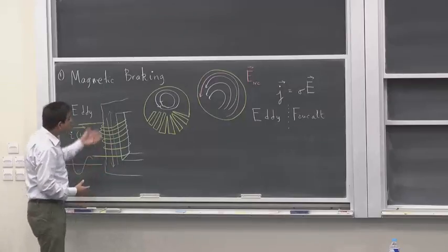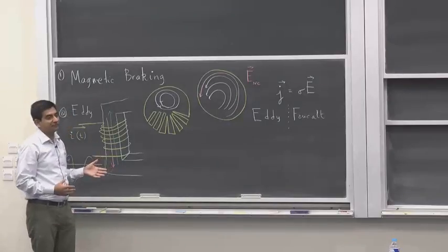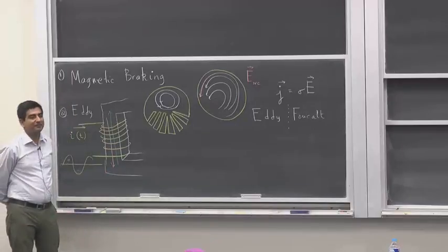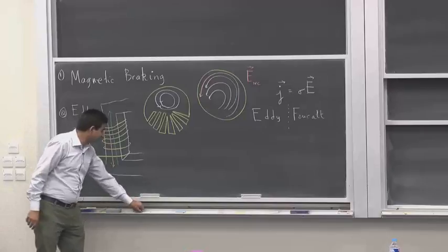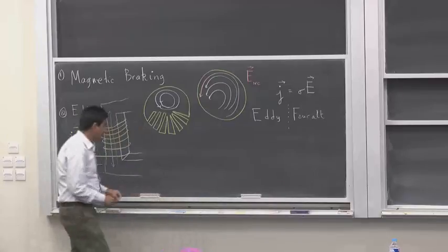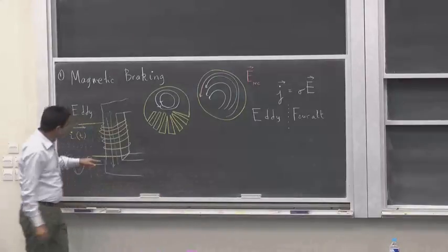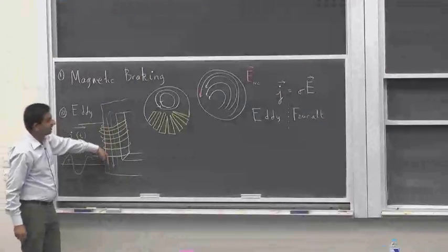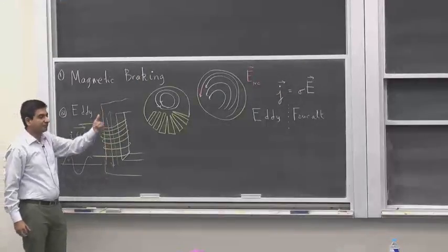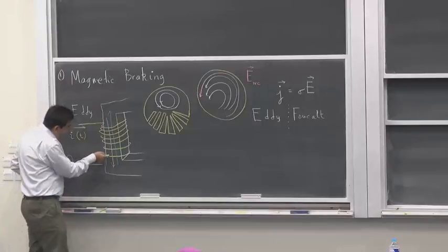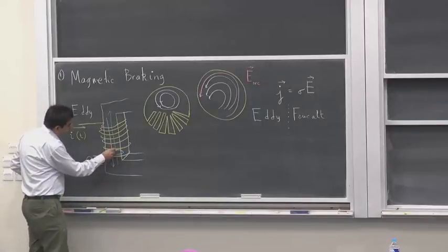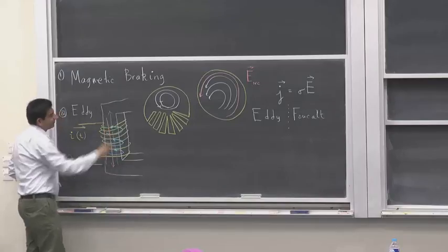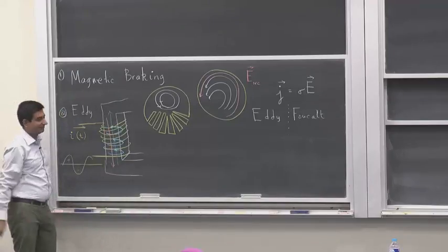So a non-conservative electric field will be produced, and that field will cause eddy currents to circulate inside this material. If in this duration of the AC cycle the external field is pointing down, the eddy currents will produce a field that's pointing up, which means that the currents will be circulating like this. So these currents will produce an upward field.